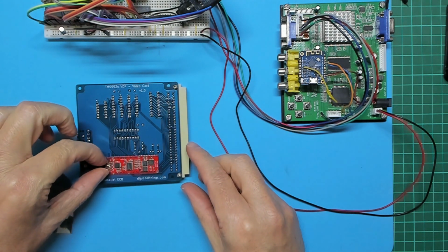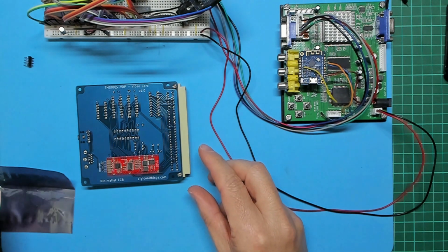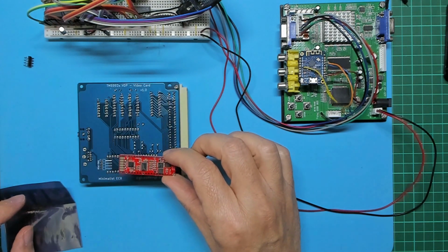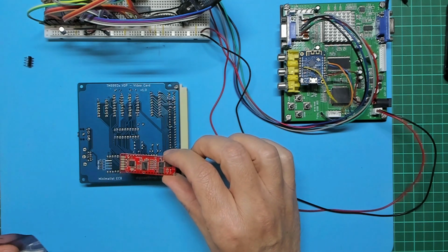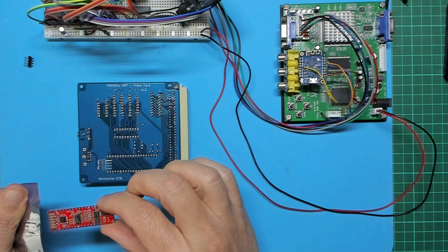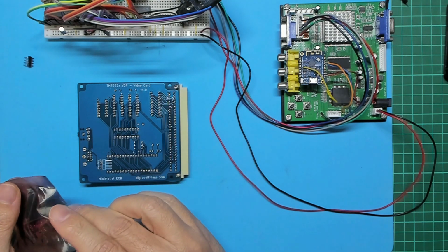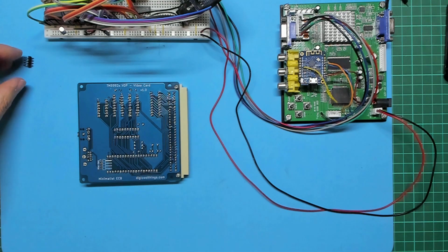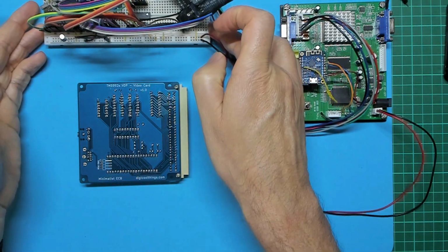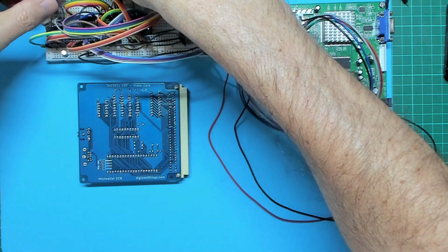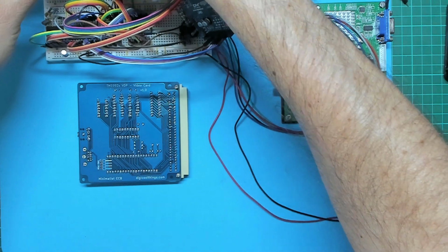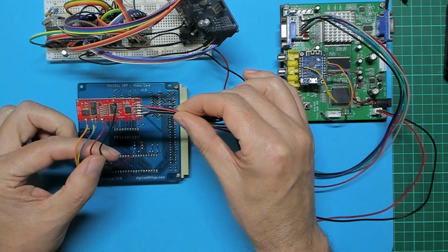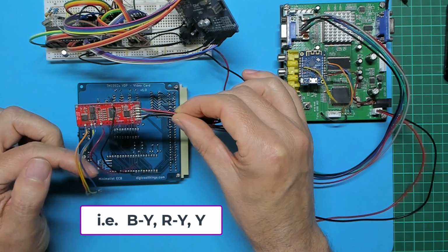But for now, I'll just temporarily wire a TMS RGB module on, swapping across the module I've been using from the breadboard circuit. This will enable me to initially test the PCB design as working before more permanently mounting the module. So I'll get the module wired in now. I'll grab the module off the breadboard, just pull that out. As you can see, there's only 5 connections. You've got the 2 power connections and the 3 video input connections.